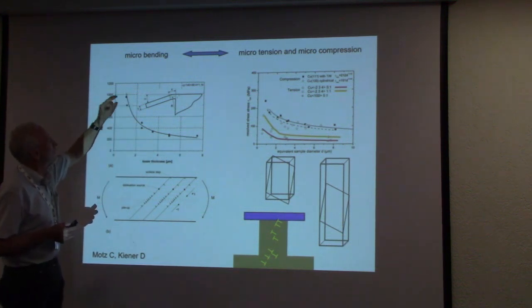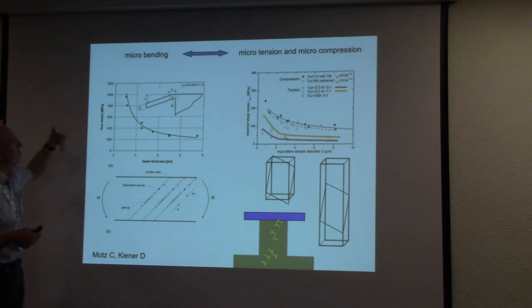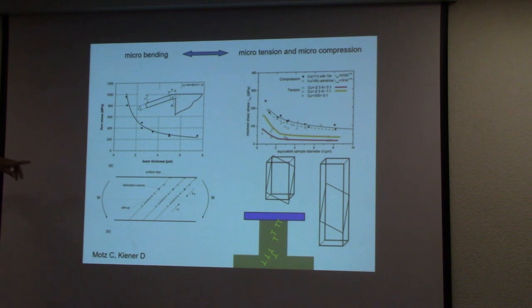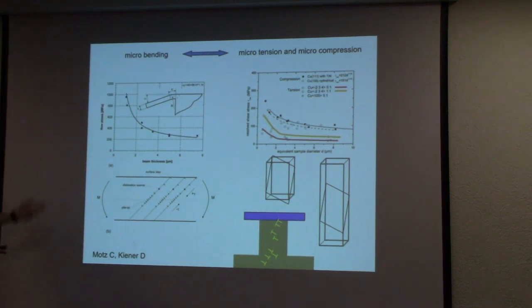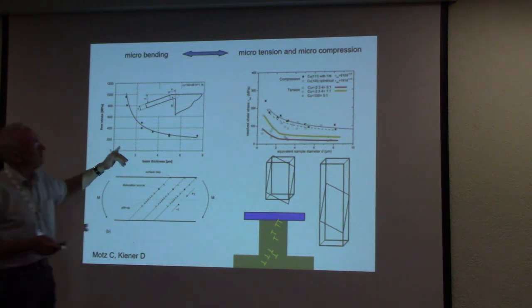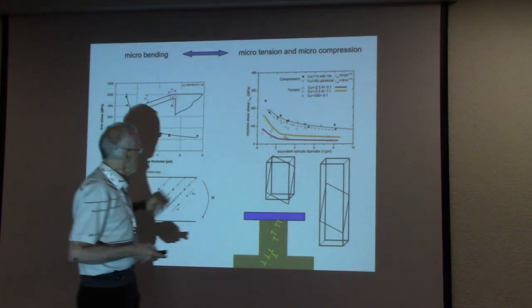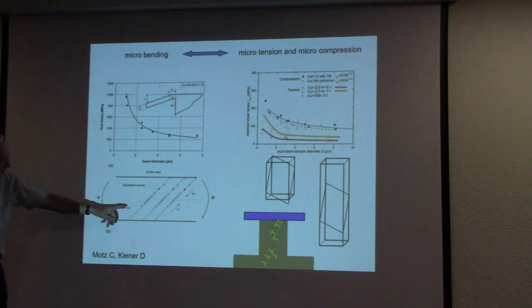This is really macro, and this was not the onset of yielding, it was really, I would say, the plateau strength during the yielding. It is 5 times higher. And the reason is relatively simple. Why bending is, we have not studied over such a large distance in the bending as in the tension experiment.